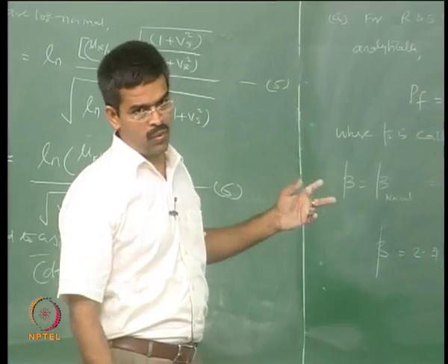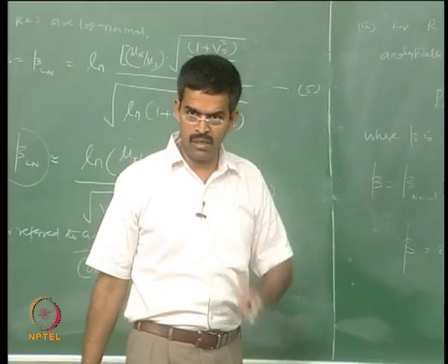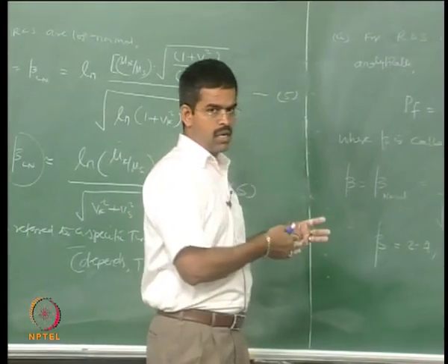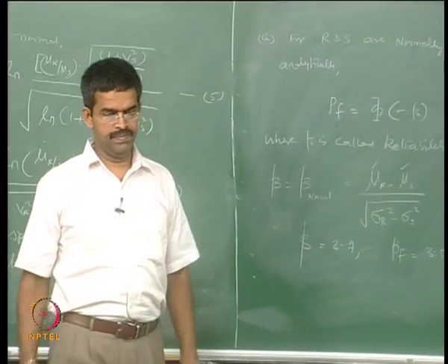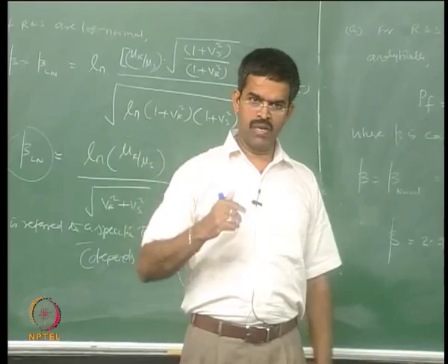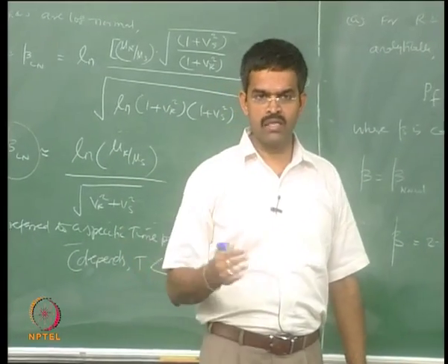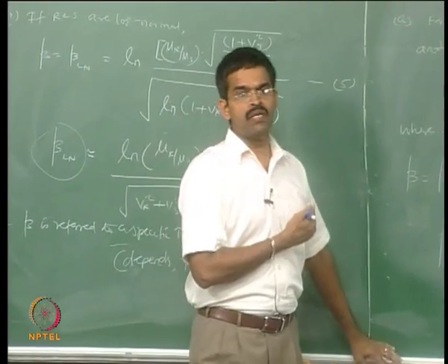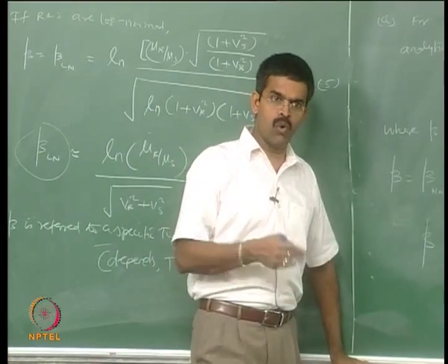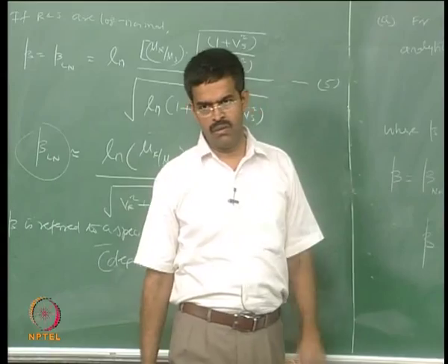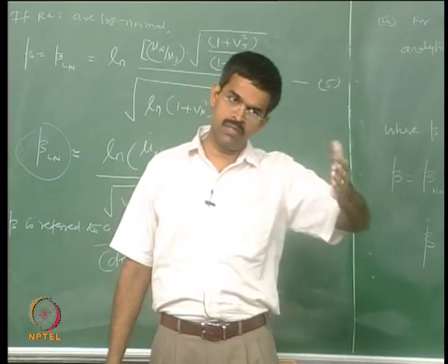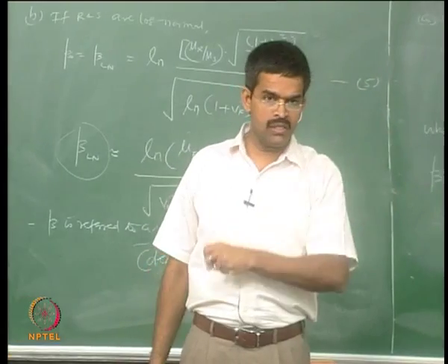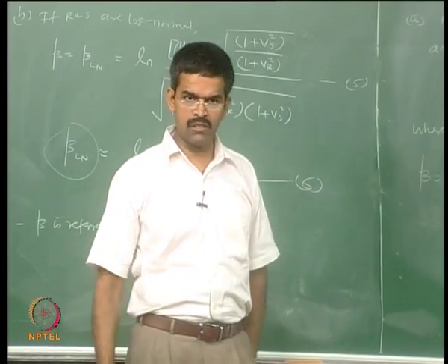There are two aspects here, one is R, resistance of the material or strength of the material, or characteristic associated with the material which has uncertainties. For example, dynamic modulus of elasticity is one amongst them, there are many. The other variable is my S, which is the load effects, load combination, load variations, randomness in nature. Mathematically modeling the randomness in your analysis, there are many uncertainties in that also.